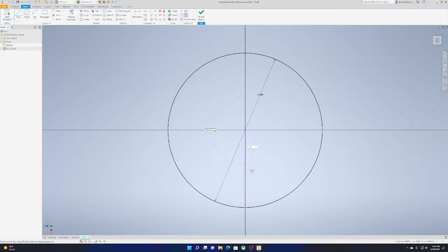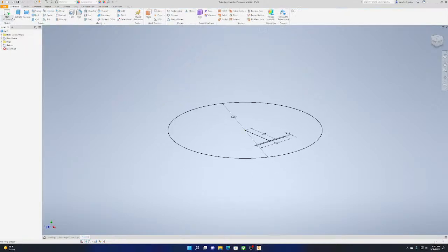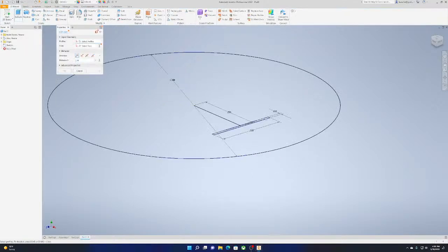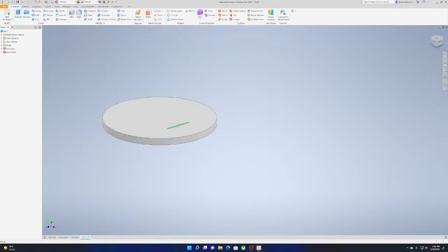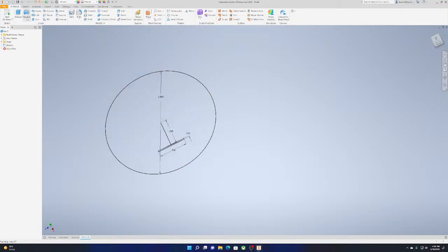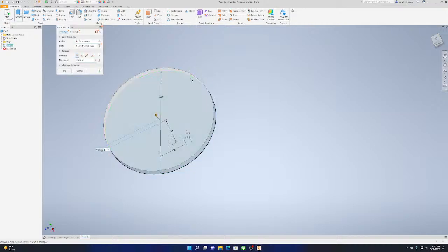So we'll go right here. And then I'll add a 2-point center right here. So I'll make it 0.01, 0.25. And we have this. And what I'm going to try and do is extrude this up really, really low. Like that. And you can see that the sketch we have got messed up, sorry. There's a hole, so I can just extrude this whole thing up by that much.